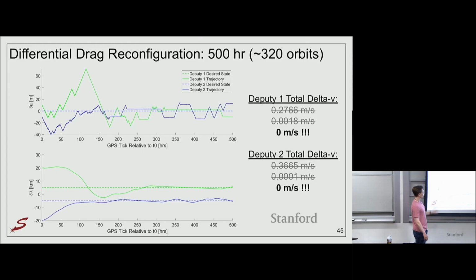The other cool thing is we can actually almost see an underdamped response going on here, which is kind of what we expect, right? Because we've limited the modeled onboard differential drag control to be less than what's actually being realized. So in effect, we're just overshooting every single time we do a maneuver, which is exactly what we find here for delta lambda.